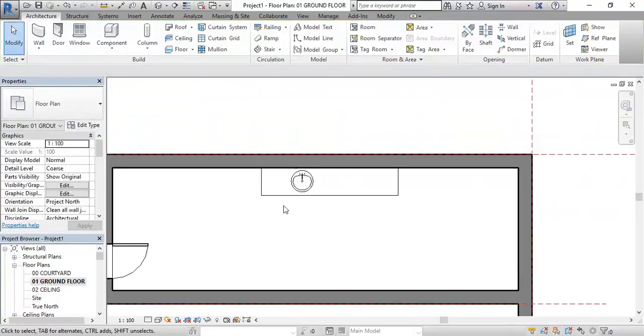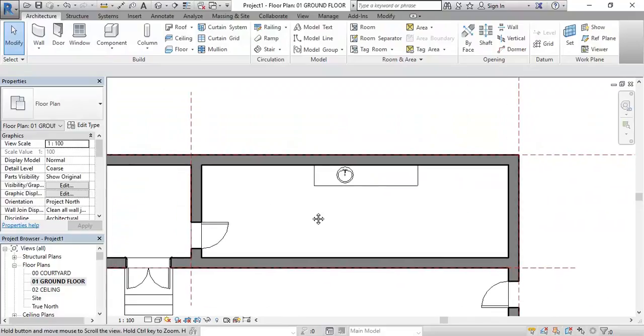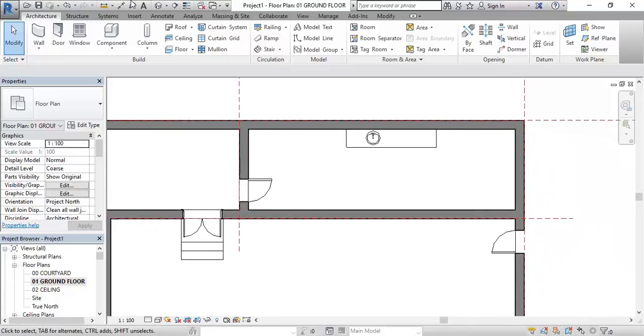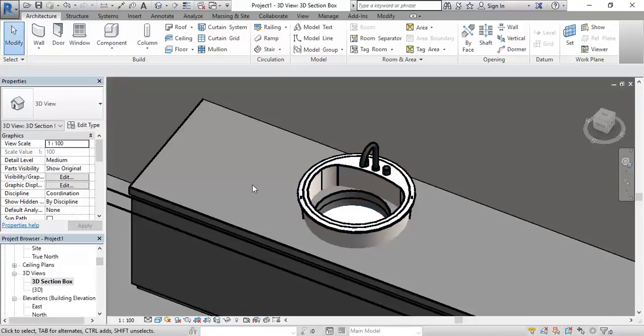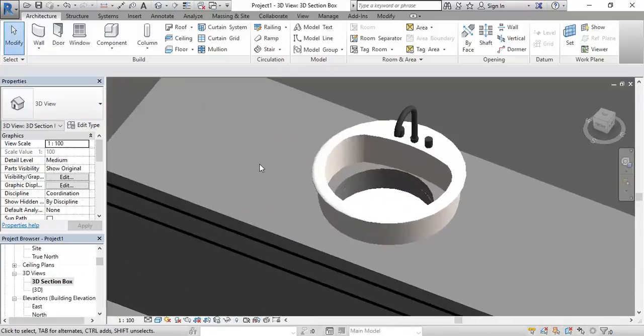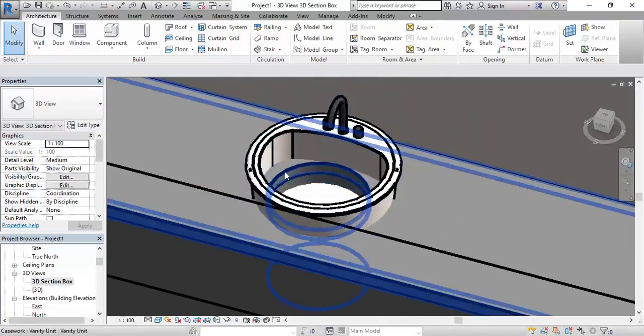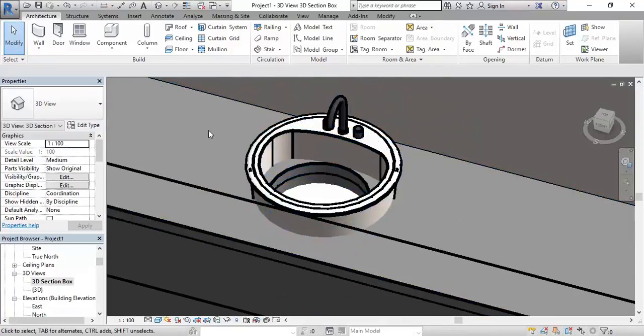So you have to make the void before you can place it. Oh, you can place them first and then make the void, but you'll need a void in the end, if it's being recessed, because this is the way you build it. So if we look at it now, in plan you won't notice the problem, but in 3D you can see. You need to make the cutout size. Yeah, exactly. That's right, exactly. The way you build it.